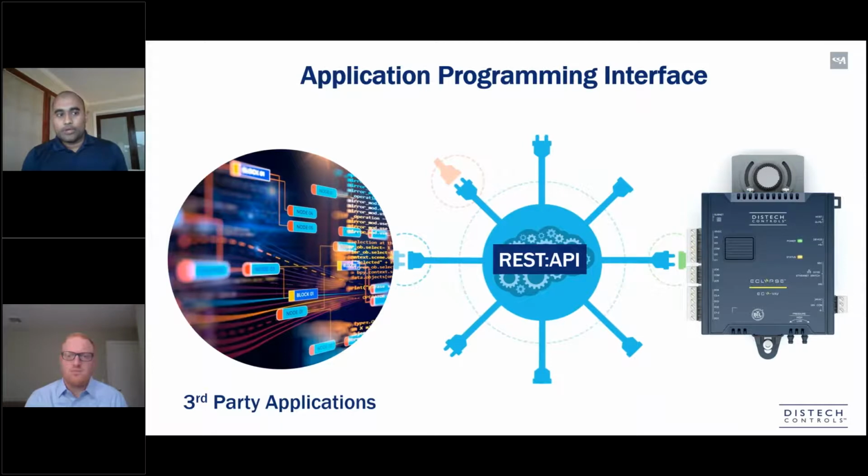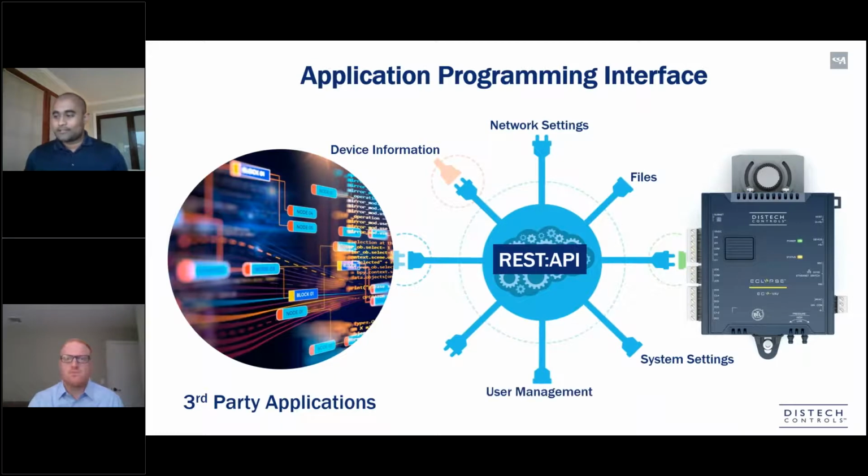So you have to watch out for controllers that are pre-embedded with an API so that you can connect them to these new apps or new sensors that are coming out each and every day. In our case, our controllers are embedded with REST APIs. The REST API is able to transmit device information, network settings, all manner of files, system settings, user management, and ultimately it's able to convert BACnet objects into understandable language for software programmers.